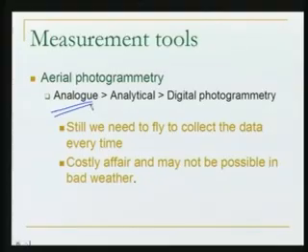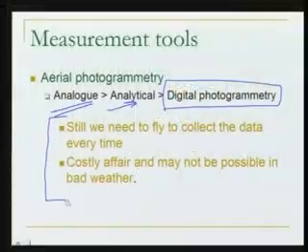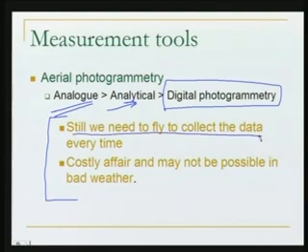This aerial photogrammetry also developed like anything. Earlier we had some analog way of taking the photograph, also processing them. In between came the analytical way, and now the modern one, just for your information, is the digital photogrammetry, where most of the things are automatic now. However, as we are writing here, still we need to fly to collect the data every time. Whenever you need the data, you need to fly with the aerial photograph, and this is not always possible.